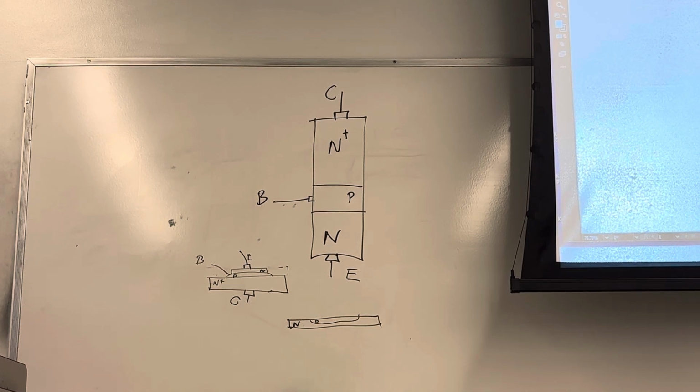It's an NPN transistor, but functionally, the parameters will be different. Beta will be different. Let me tell you what the beta will be. It's called beta R, reverse beta. Beta R's are 1 to 10, so it's so small. A gain of 1. You don't want a gain of 1 transistor, or a gain of 5 or 6. But if you put them backward, that's what you will get out of it.